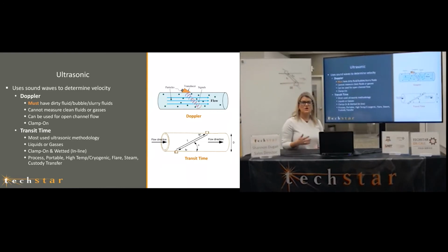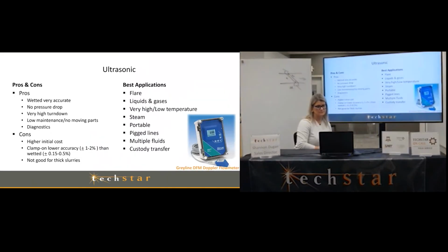These transit time meters are the most used today in terms of ultrasonic. They're very flexible, and you can use them on gases or liquids. Also for a wide range of applications, from water, wastewater, custody transfer, flare gas meters are ultrasonic meters normally, and very high temperature, very cold temperature applications. Pros and cons.